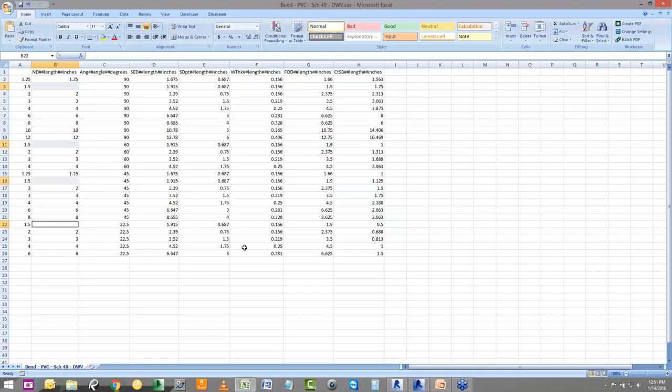All this information in the lookup table can be reorganized, it can be in order, it can be out of order, it really doesn't matter because Revit is going to be looking for the values that you have listed here. Obviously this gets a little more complicated when you get into other types of fittings, say upright wise or double wise, cross fittings, that sort of thing. There will be obviously more control there and then other equations that control other aspects of it.